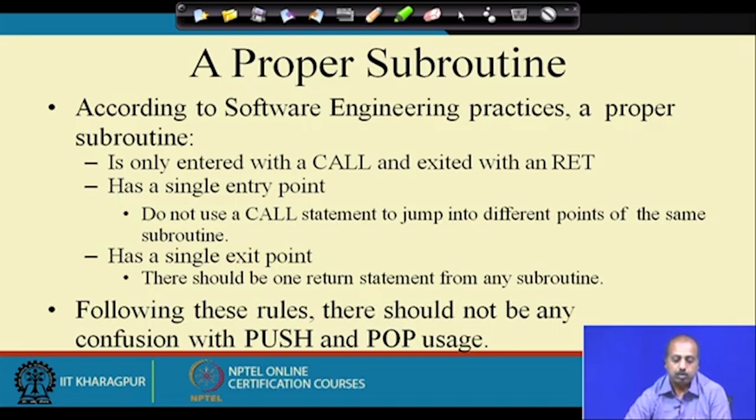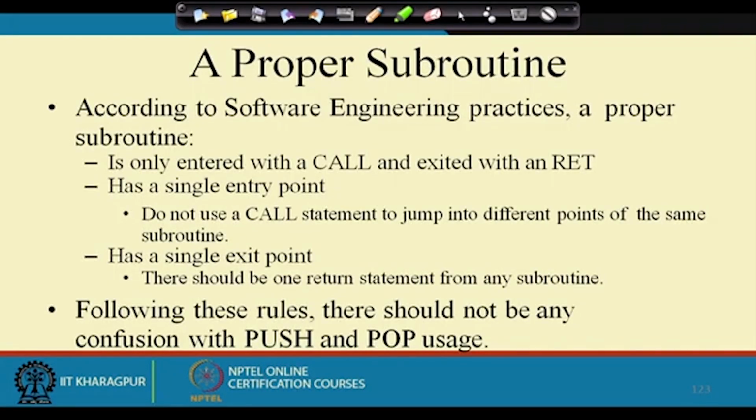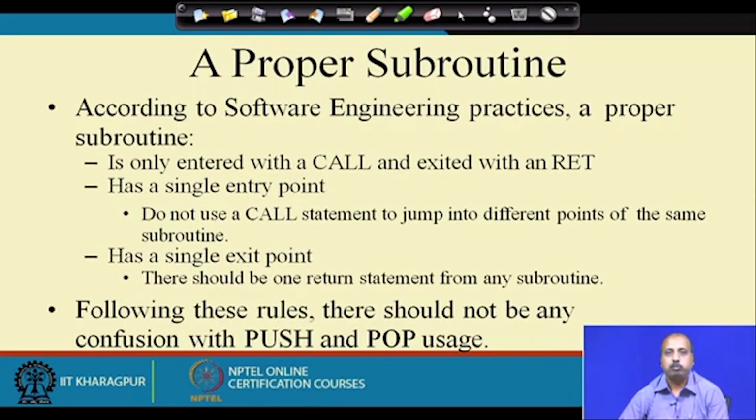So, do not use a call statement to jump into different points of the same subroutine. You should also have a single exit point; there should be only one return statement in any subroutine. If you have multiple return statements, that makes the readability of the program difficult. So, we should try to redesign that subroutine so that there is only one exit point. That will help in making the program easily understandable. Following these rules, there should not be any confusion with push and pop usage also, as their numbers should match. If we follow all these rules, then we will be able to design a good subroutine.